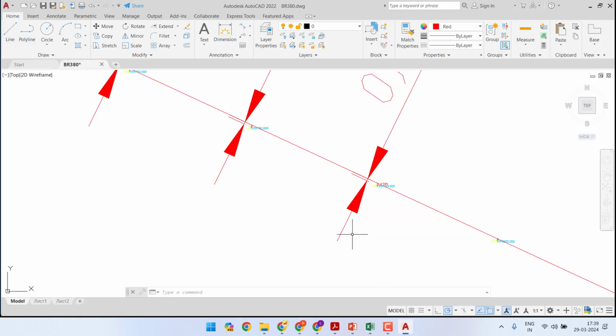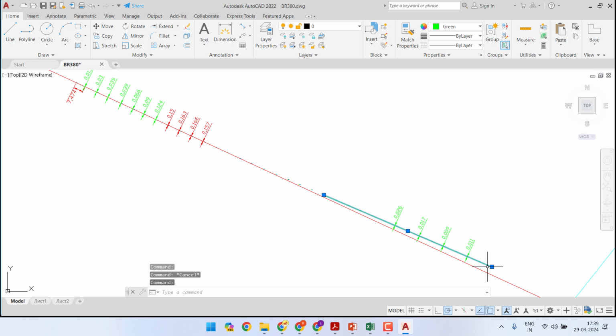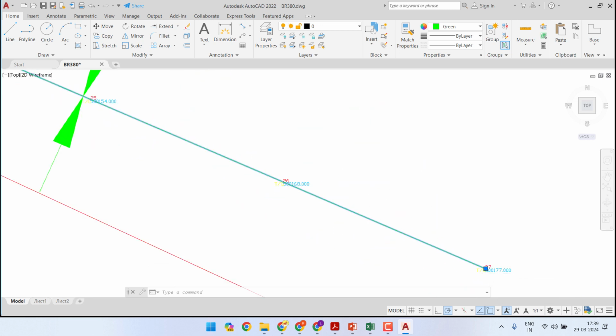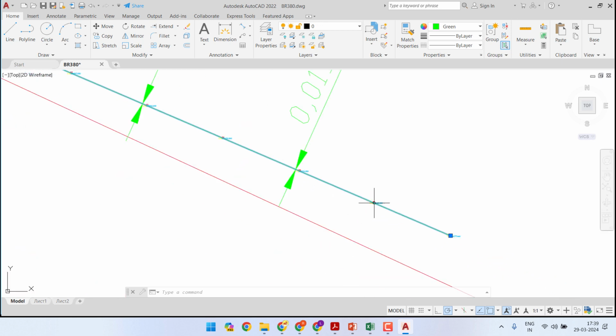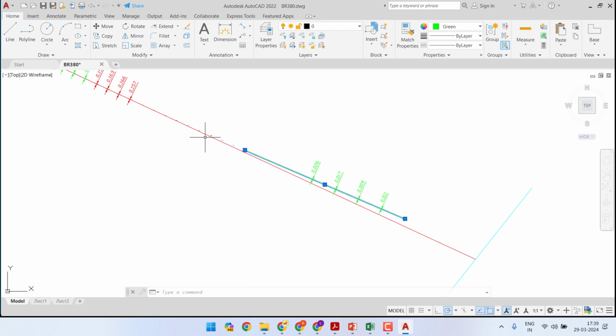In redesigning the whole curve, we already have the first terminal tangent, which is A1 to A2, the line that is following along A1 A2. We will need to determine the second tangent, and this was the exercise that we were going to do. We will continue it in the next video. There may be many options for selecting a good point for the second tangent. We may select 27, we may select station number 26, we may select station number 25, and what will be the second point which we will join. So we will see that in the next video.